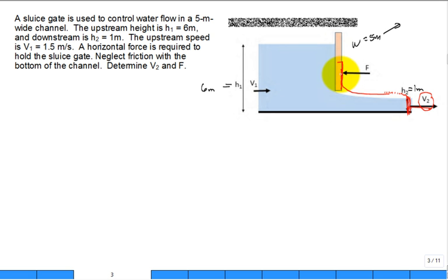So when I come along the outside of the sluice gate, it's all just atmospheric pressure. Oh, but I have one point load applied to it, and that's part of my control volume. Then I come up and I go around. I know that there's probably a hinge up here and a pivot, but then you would have to worry about that. You can't just come up and cut through the middle of the gate right here, because there could be some forces through there. You need to cut through the air. Got it?